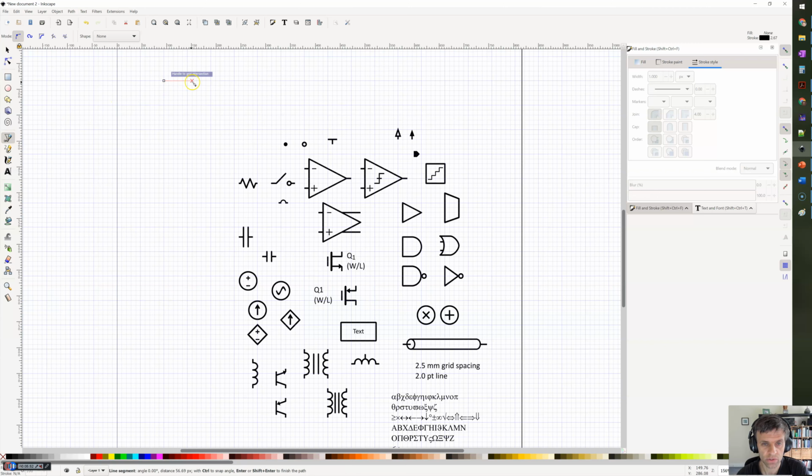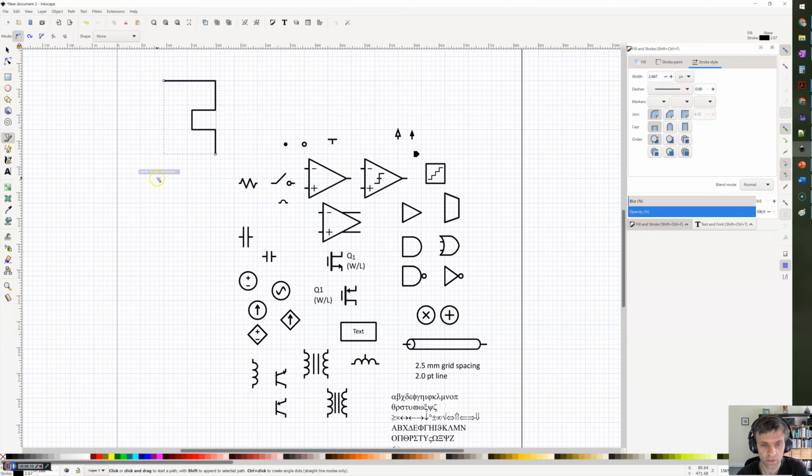That's because it lets you draw a multi-segment wire continuously. And you'll see that I'm snapping to the grid. We'll discuss snapping shortly. But with each vertex of the path, I'm just left clicking once. And then when I'm done, I right click. Make sure you just click once in order to draw these lines.